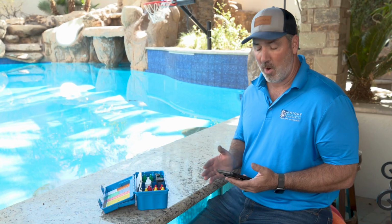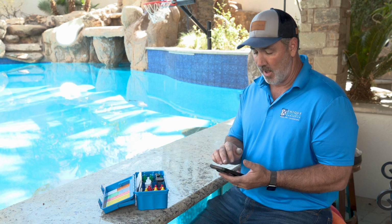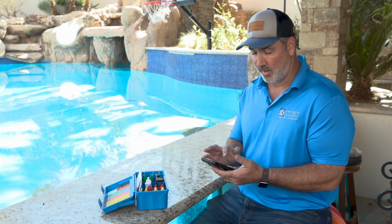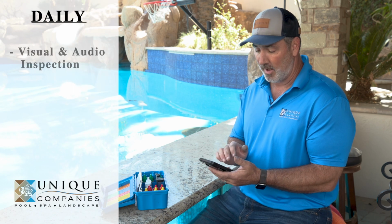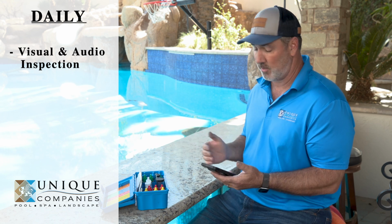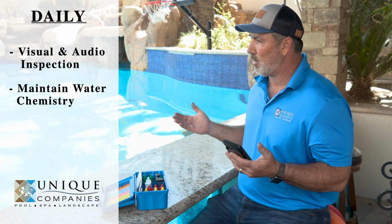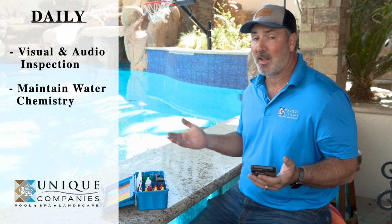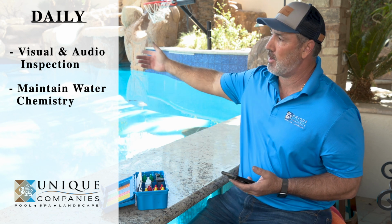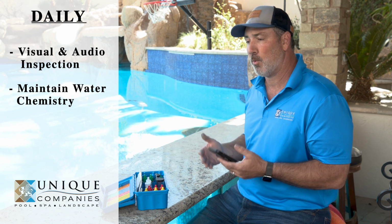So other pool service requirements, you might be asking, is it daily, is it weekly, is it monthly? What are the things that we have to do in those increments? Again, in our orientation checklist, we have our pool service requirements that you'll get a copy of. On a daily basis, I have visual and audio inspection of the pool for potential issues, and maintain proper water chemistry. So what does that mean? Do you need to go out and look at your pool every day? It's recommended. What happens if a pump is on, draining water into the side of the pool? You're only going to catch that if you walk out and look at the pool or look at the equipment.